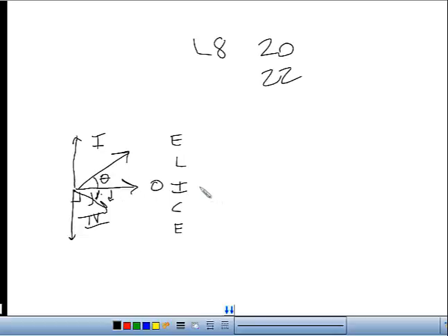In a parallel circuit, the one thing that's the same everywhere is voltage. So using the same mnemonic, Eli the Iceman, we can see that the capacitive current vectors or power will be positive angles, and then the inductive will be negative angles. We need to be able to keep track of the positive and negative, especially once we move into a more complex circuit, combination circuits where things are both in series and parallel.